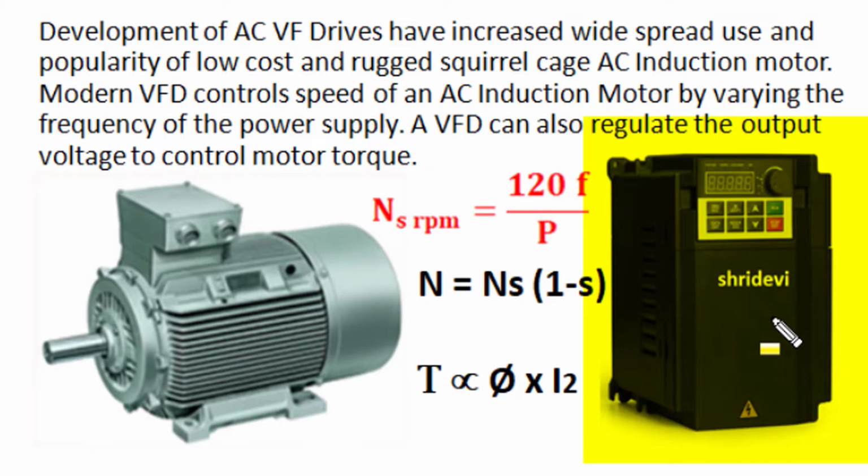And all that improvement not only increased performance, reliability and efficiency of variable frequency drives, it also reduced the cost of these modern electronic variable frequency drive supplies, and that has increased the use of this low cost and very rugged squirrel cage induction motor in the field of variable speed load applications.